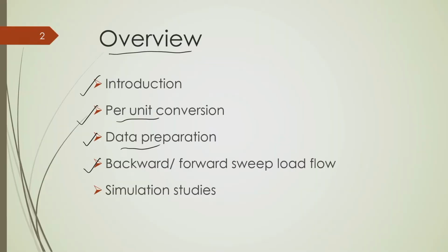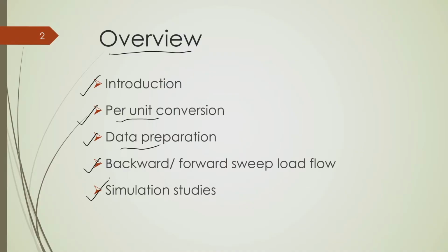I will illustrate what we mean by load flow or power flow analysis, and what the forward and backward sweep load flow algorithm is. And I will also show you some simulation studies for some typical distribution networks, the results that we got from this power flow analysis.